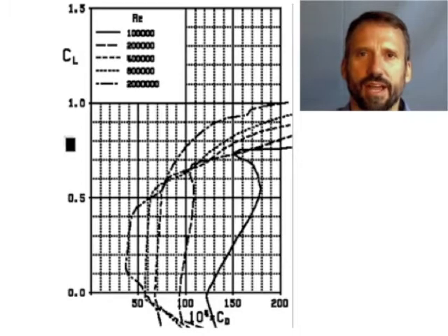Between World War I and World War II, the community of aviation enthusiasts and industrialists had a lot of enthusiasm and a lot of talent, but not much money. So they spent a lot of their time investigating fundamental issues and recording those results in the form generally of trade-off curves. For example, the National Advisory Committee for Aeronautics, the NACA, published catalogs of airfoils. These listed the coefficient of lift versus the coefficient of drag at different Reynolds numbers.